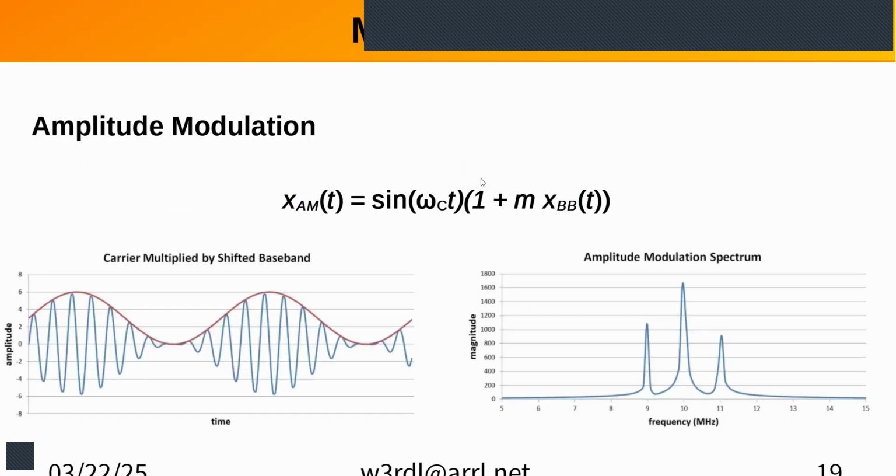When we amplitude modulate, the picture down here just shows you're varying the amplitude of that carrier wave anywhere from 0 up to its maximum. If you look at that on the spectrum, you're just going to see the carrier and the two sidebands. I'm not sure why in this case they're different amplitude. Shouldn't be. It could just be the point in time at which that snapshot was taken. But as the modulation changes, you will see those things move and go up and down.